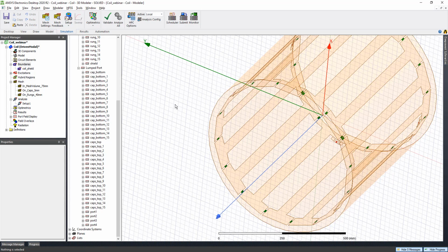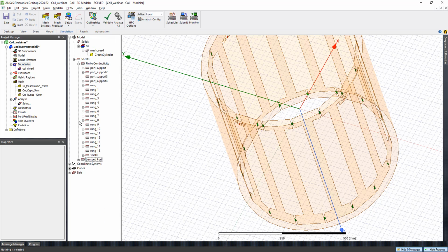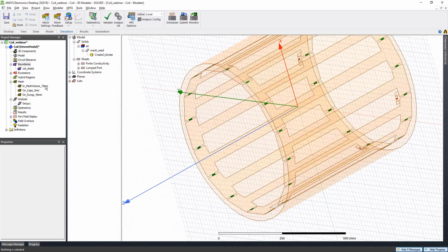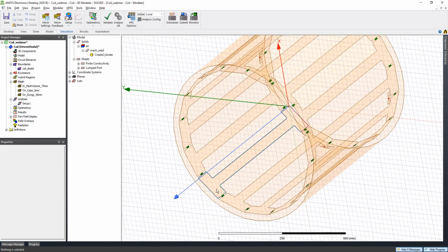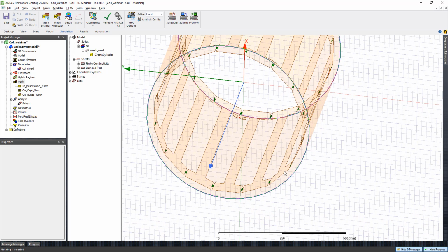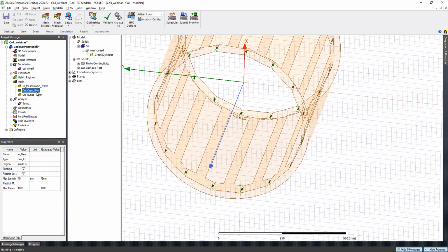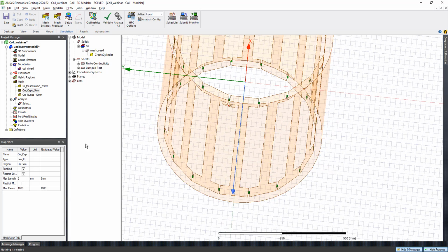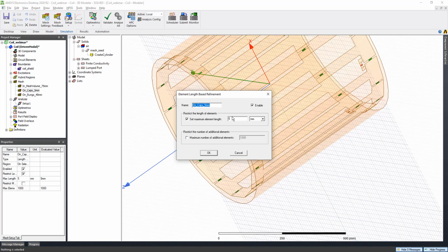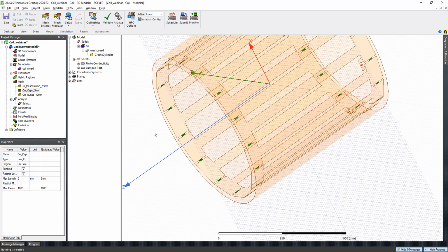Another setup we have here is an airbox. Here I'm having multiple different mesh sizes because I'm trying to reduce the time for the simulation. With larger structures, I just give a larger mesh size. With smaller structures, I just have a smaller mesh size. And you are always welcome to change this to anything that you like or to have a higher accuracy.